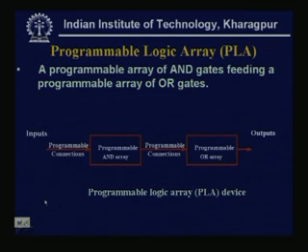And programmable logic array, PLA. Here this is more flexible, as both the arrays, the AND array and the OR array, can be programmed. See, this is a programmable AND array, a programmable OR array, and the connections from the inputs as well as the intermediate inputs of the OR array can both be programmed. So, this is called the PLA.